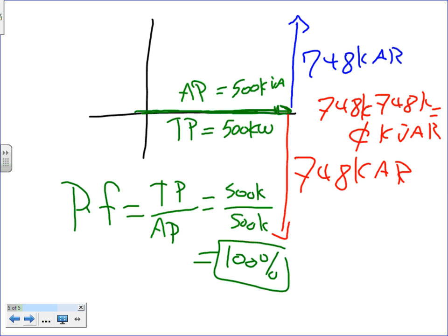And where would you use the synchronous motor, guys? In bigger plants, where we have tons and tons of motors running. You can run another motor unloaded, and that will be the synchronous motor. You over-excite it, adjusting the excitation to give you a certain amount of kVAR to solve the problem of the power factor. Any question, guys, about the power factor? Two ways: capacitors or synchronous motors.